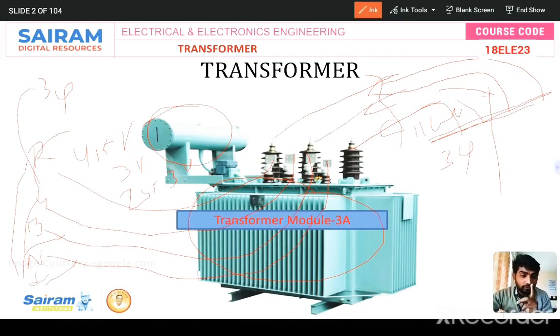Similarly here also, if you fill the transformer tank completely with oil, sometimes it may blast, because there is no place for the vapor, right? And it will also produce some amount of gas. And these fins will be there, right? This number of thermal fins are for cooling purpose or for circulating the oil.